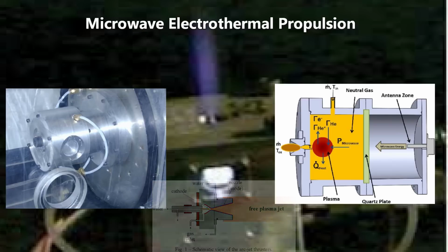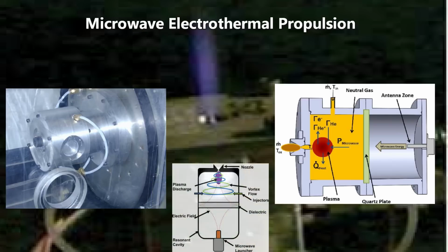To make a microwave electrothermal rocket engine, you need to allow a gas to come into the heating chamber tangentially, creating a vortex effect and keeping the engine cool. For water, this could be done with sonic vaporizers or just heating it to steam temperatures. 100 Celsius is nothing to a rocket engine.